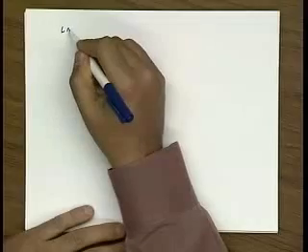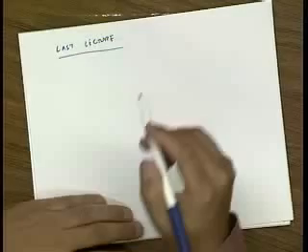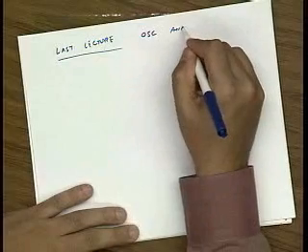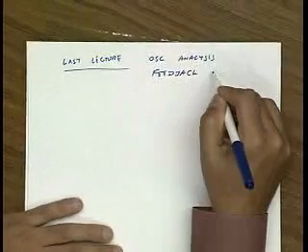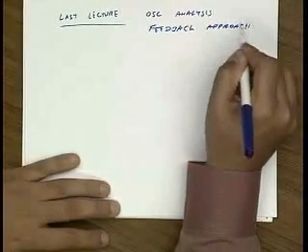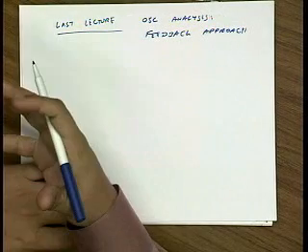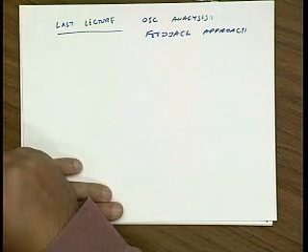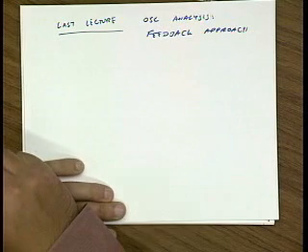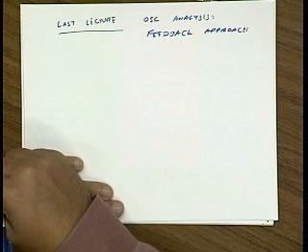All right, so let's summarize what we did last lecture. Last lecture, we used the feedback approach to find the conditions under which an oscillator, a circuit in general, will become unstable, more specifically a tuned circuit, how we could place its initial poles in the right half plane so that any kind of disturbance in the system would cause these poles to ring and grow in amplitude.